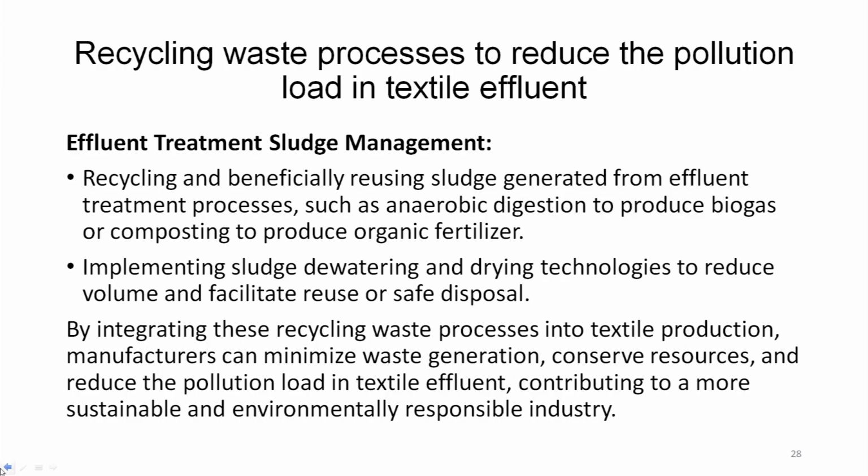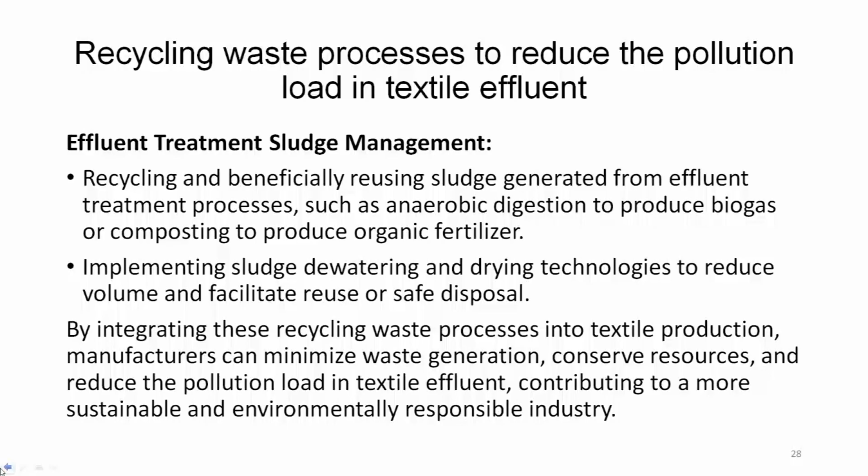Now, we know that biogas of course is very important component or byproduct of anaerobic digestion, apart from what it does for the degradation of the organic pollutants. But at the same time this can be also used for organic fertilizing, the composting of this sludge. So, sludge management also is very important, and we dedicated one full chapter or lecture on sludge disposal and management. Implementing sludge dewatering and drying technologies is also important.